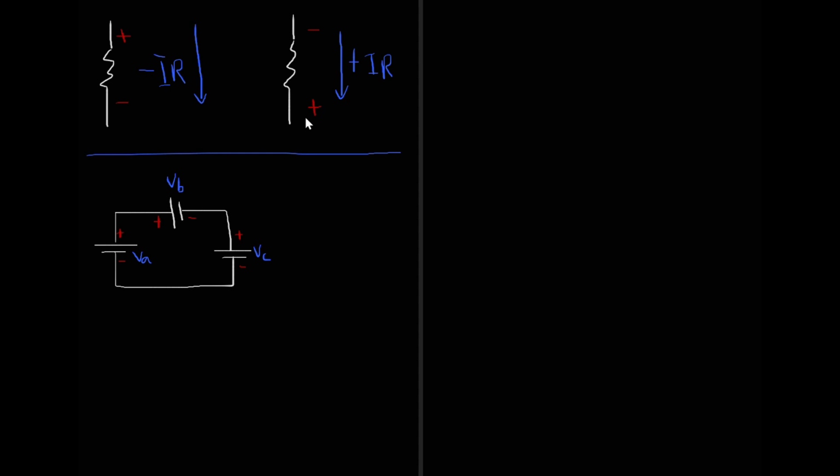Now, to clear something up, some people switch this around. So we're doing it this way, or my way. I prefer doing it like this, because if it goes from positive to negative, theoretically it should be minus, but some people put it as positive and they just do the opposite, which I don't understand why, but it's up to them. So let's say that we want to find the sum of all the voltages that are flowing in the circuit right here. We're going to apply Kirchhoff's voltage law.